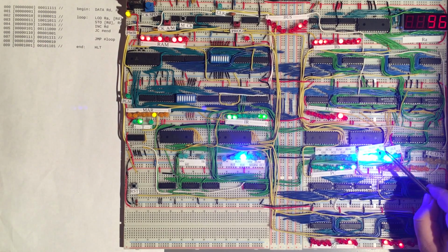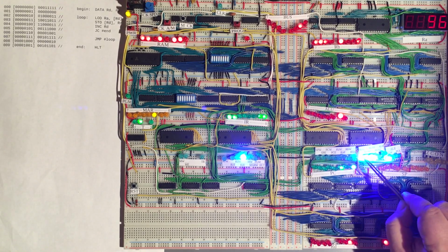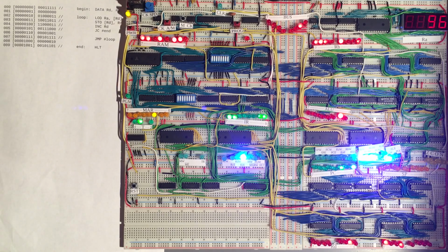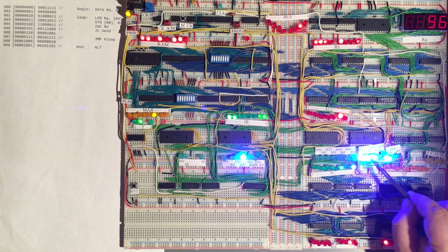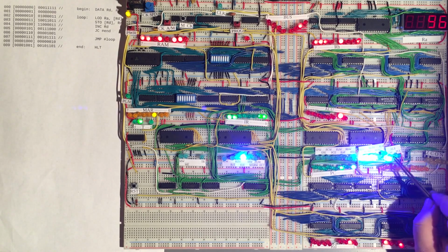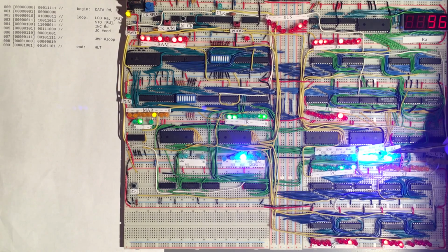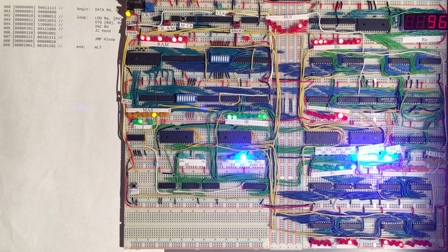And so the control signals here, you can see the B input is not being asserted, and so that means the B input isn't coming from the B register, but is instead hardwired to 0. But we are actively asserting the ALU carry in signal. And so we will be adding a 1 to whatever the ALU is calculating. And then here are S signals, which we read back to front, remember. So S2, S1, S0 are set to a low, high, high, which corresponds to an A plus B operation. And so the result of that calculation will, in the first stage, be stored into this ALU register, which we have here. So the ALU register write signal is also being asserted.